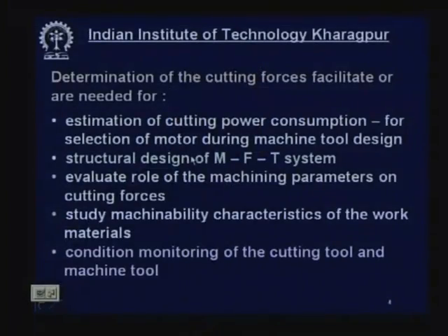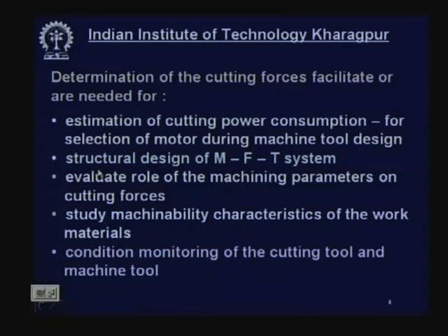Estimation of cutting power consumption for selection of motor. You know, machine tools are driven by some motors, and what should be the specification of that motor? When we design a machine tool, we design the power drive, and in the power drive we have to select, say, a motor. What should be the power of the motor and what should be the RPM or speed of the motor, and that requires knowing the cutting force.